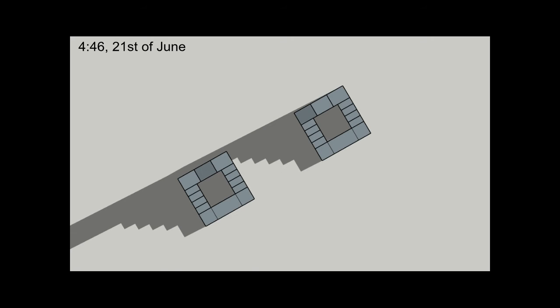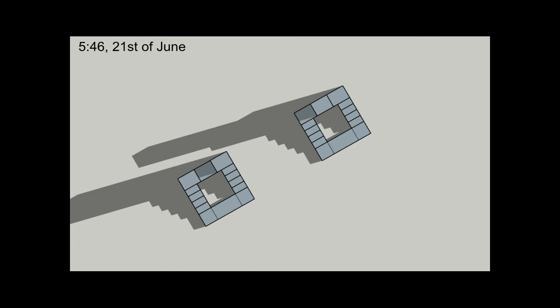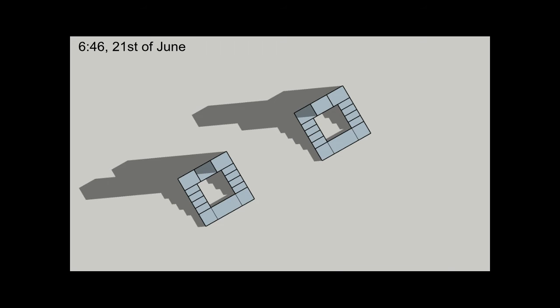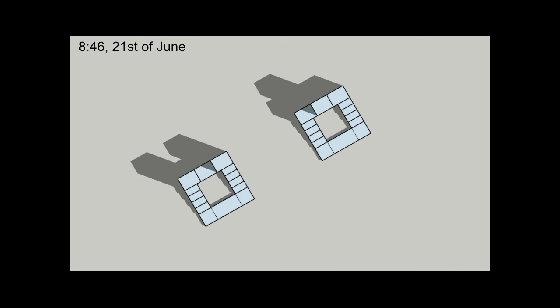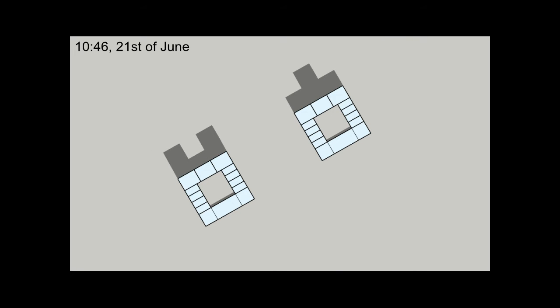The analyses show that there is very little difference between the total amount of shadow cast between the two options. Option 2, however, casts a slightly wider shadow. In addition to this, Option 2, because of the shorter and staggered heights facing the west, is expected to be better for the dispersion of the westerly winds arriving from the west.